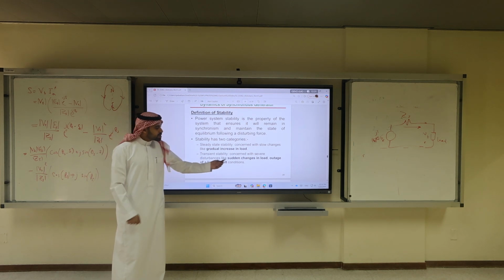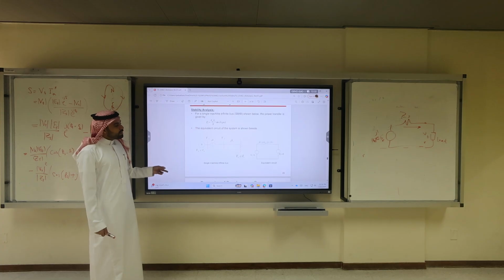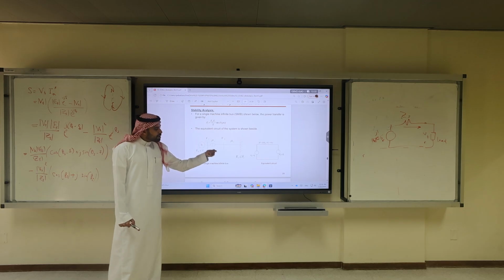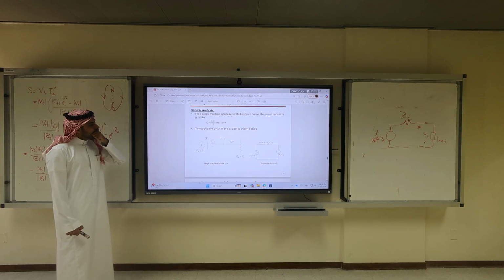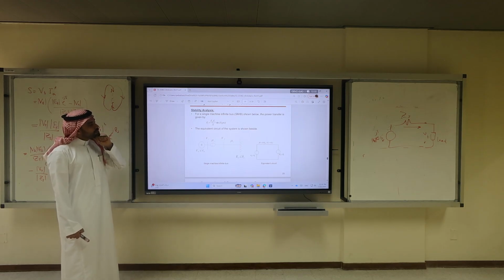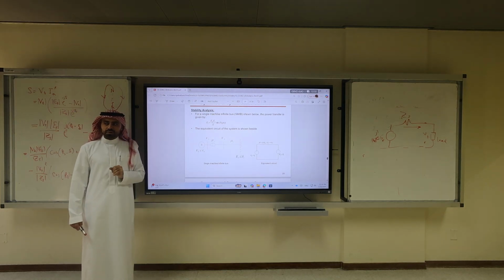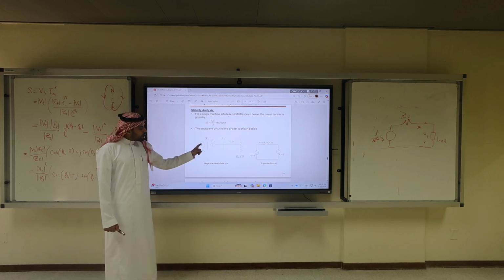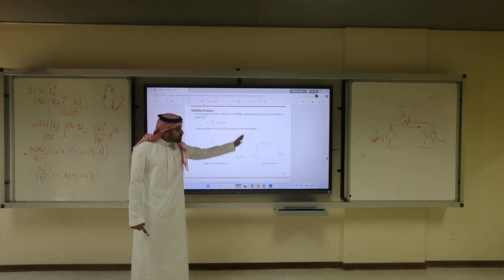The transient is too much that there is a severe disturbance. It turned out that this has to do with not only the generator, it's also the transformer and the transmission line. But hold on a second. I already told you that the power has to do with X of S at the denominator. But this is just the power that's leaving the generator. But you as a power engineer, you care about the power that's leaving the generator, going through the transformer, going through the transmission line to the infinite bus.